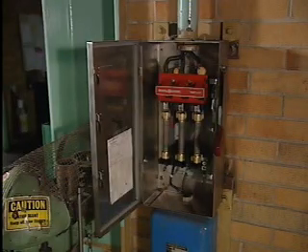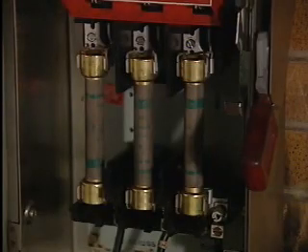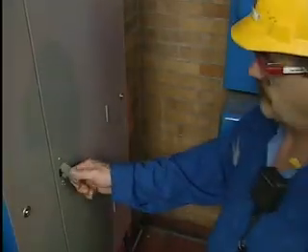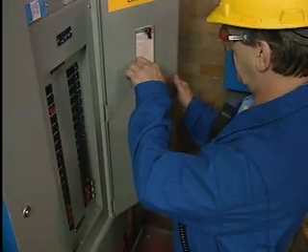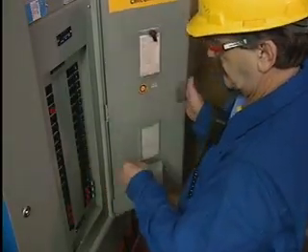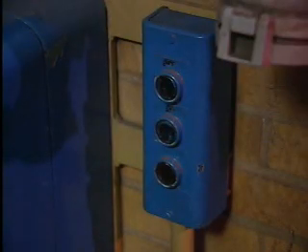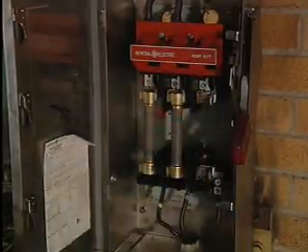Strong arcs can burn or blind a person nearby. Arcs can be caused by a number of conditions. One common cause of arcs is pulling out one end of a fuse that's carrying current. To prevent an arc from forming when a fuse is pulled, the current flow through the fuse should be stopped first. This can be done by turning off the power to the fuse or by turning off the equipment that's connected to the fuse. If there's no current flowing, an arc cannot form.